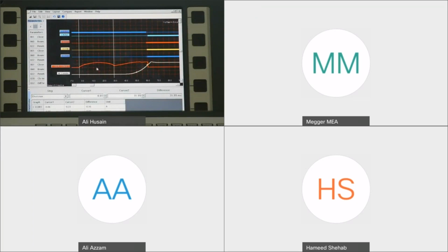So this is showing me that the coil took almost, I would say, 32 milliseconds to reach, or the plunger to reach its final stop. Then another, I would say, if I took the secondary cell for the final operation, another 31 milliseconds for the mechanism to do its part of opening or closing the breaker. In this case, closing the breaker.